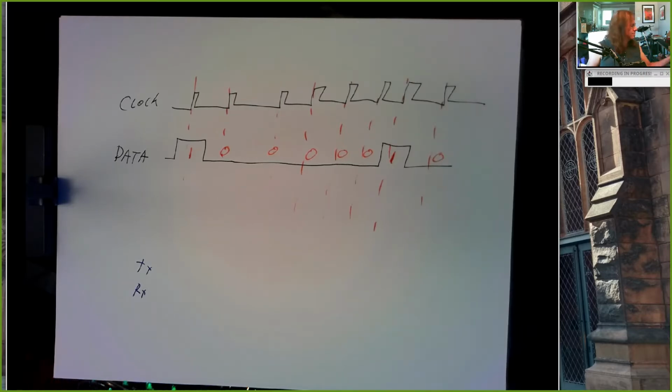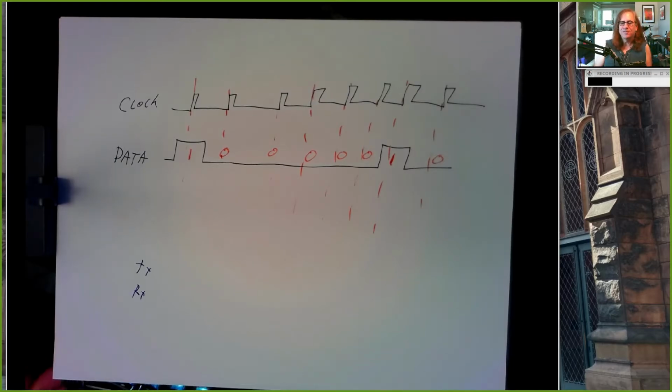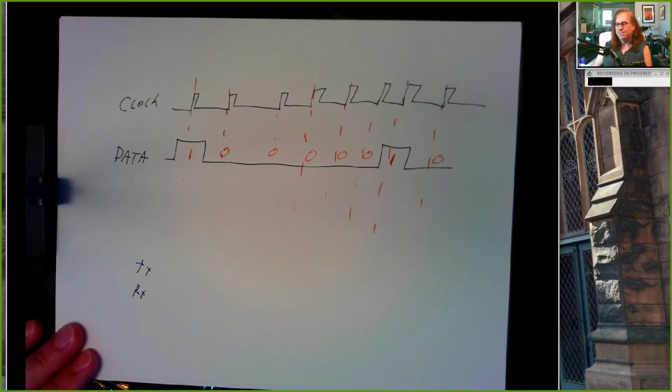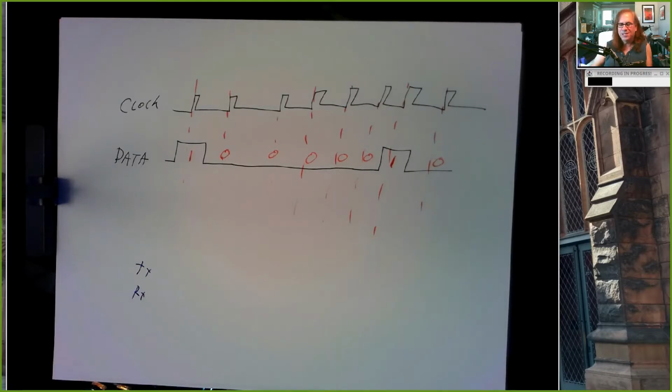So it's just easier and cheaper to make a microcontroller that works in serial and then sends it to a translator for USB. Serial is a really low bar, low cost of entry. For example, if you wanted to hook two Arduinos together and have them share information, a really easy way to do that is through two serial lines. Take a transmit and receive, take a receive and transmit, hook them together, and it costs you 2 pins, which is not a lot, and you can send whatever you want, bytes or words of information.